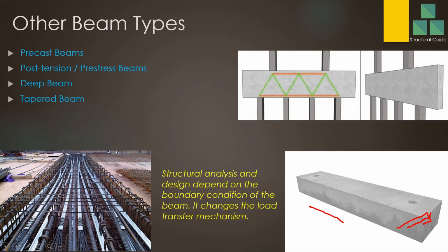That is the process of construction of post tension. In pre-stress beams, you do the tensioning of the tendons early. You do the tensioning, then you put the concrete, and then we release the ends. Then the relevant stresses will be developed in the beam.